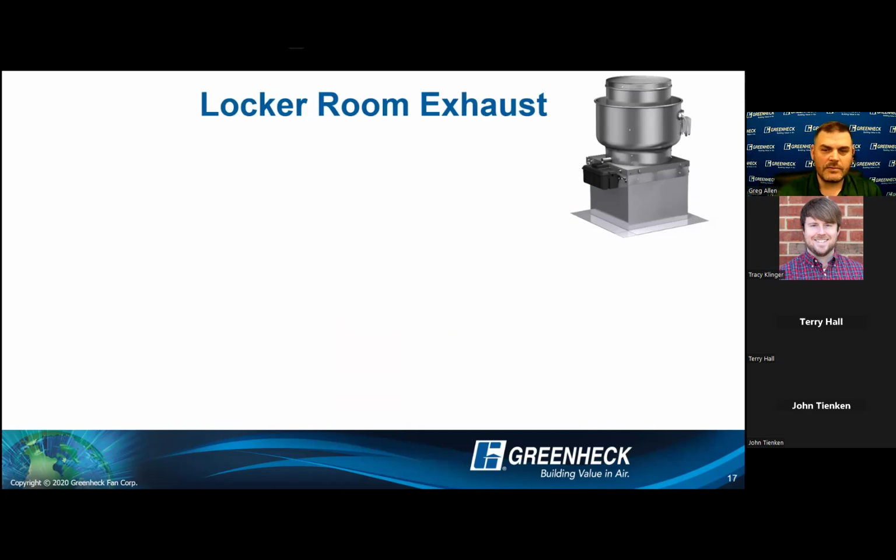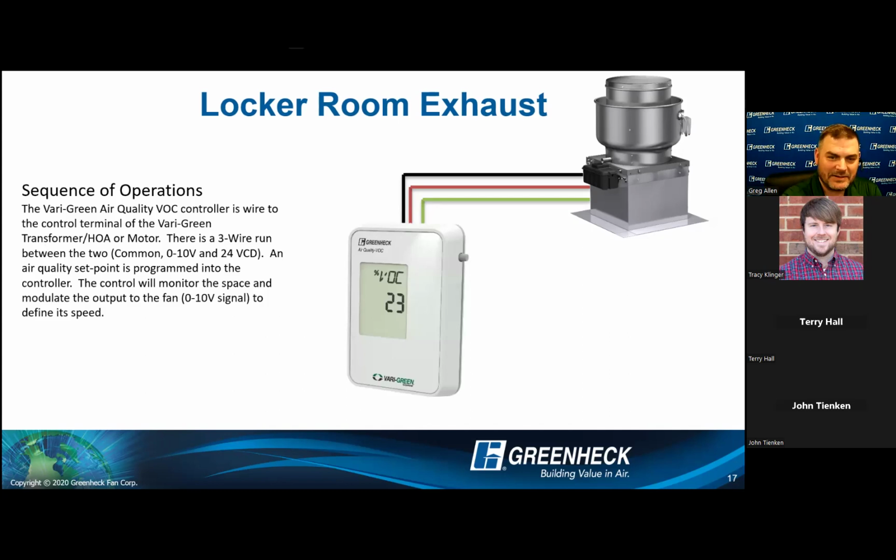All right, so let's go a little bit trickier. Now we're exhausting a locker room. We have a beautiful rooftop exhaust system there. And I got my wiring, and there it is. For this scenario, this locker room exhaust, I am moving different amounts of air depending on my criteria, and the controller I picked is a VOC, or volatile organic compound controller.